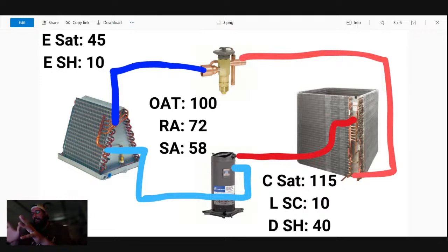No, this is not. I'll just tell you this one up front. It's not an inefficient compressor. Low delta T. Yes, it is a low delta T. Lower the indoor speed so we can condensate more humidity.